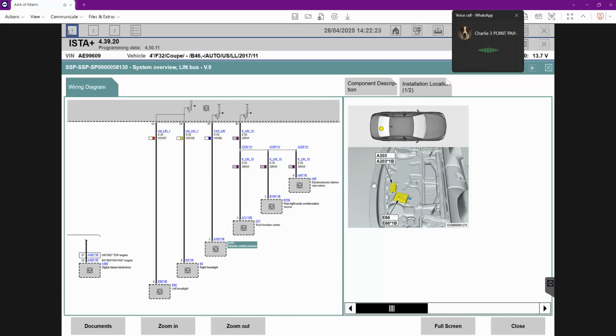Oh, it's in the car. Yeah, okay, I got you. It's inside the car, in the back shop. It's located either at the trunk or somewhere. Is that a convertible? It's a regular coupe. Okay, good. So it's either in the trunk or the bottom floor, or somewhere near the windscreen. Just check if it has water damage or if the wire is disconnected. Examine it properly, because one of the wires in the LIN bus is disconnected here. So check the remote function actuator to the BDC, the LIN box. Alright, let me check. Let me know.